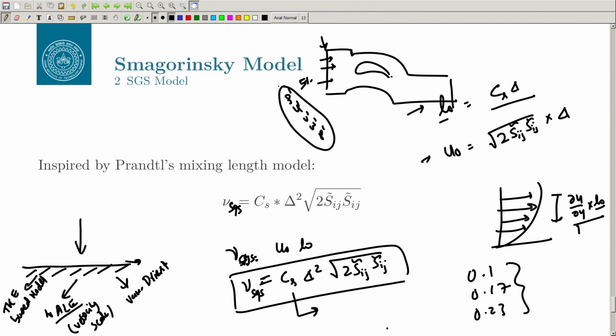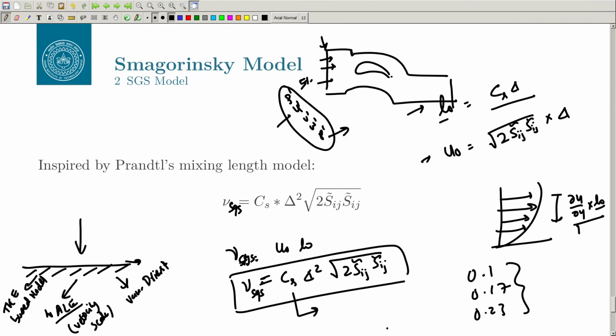So, there are ways to provide your input turbulence. You can have a precursor simulation where you can find out these fluctuating quantities based on the turbulence level, or there are approaches like digital filter. There are approaches by Lund where you recycle and rescale. The other thing is that it needs to be changing with time. So, it has to obey certain statistical properties of turbulence, and it should change in time. Every time you cannot have the same fluctuations. So, it has to be correlated in time, and it has to be correlated in space.